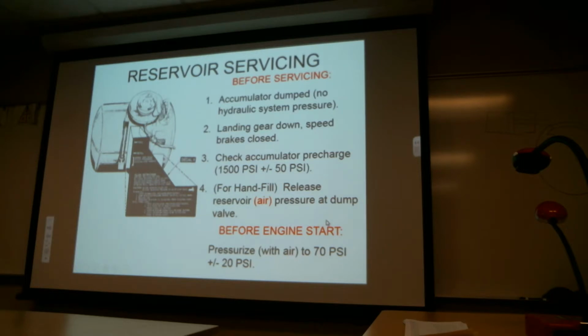So what you're doing is, before you even use a pump, if there's a gas charge in the accumulator, the gas charge is always there. When you start the pump, you're pushing fluid into the accumulator to further compress that gas charge. So now you're holding the fluid that's being delivered by the pump under the pressure of that gas. When you use an actuator, you're using the gas on that side of the diaphragm or bladder to push the fluid to the actuator. So when they talk about the pre-charge, that's really the gas pressure in the accumulator.